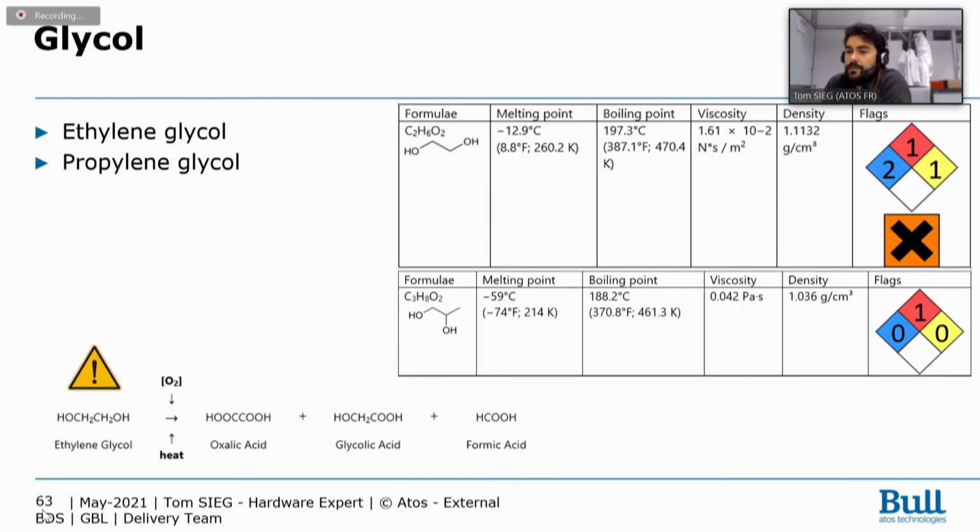So the glycol will not go onto the system itself, not on the server, not on the login node, etc. All these parts will be protected in case of a water-cooled door or other water-cooled solution in the rack itself. And again, normally you will have a sensor in the door or under the rack to be advised in case of any leak.